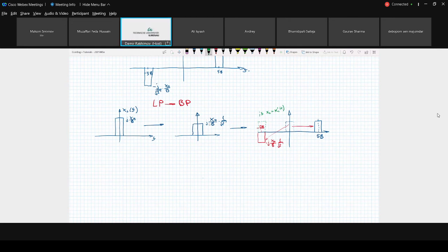Yeah, this is right, that you have one signal and then you split it in two, but you split energy. You split energy in two, not amplitudes, but energies. And amplitude will be the square root of energy. And for this reason, we have square root of 2, but not simply divide by 2, because we care to have the same energy before and after. Not the same amplitudes, but energy.